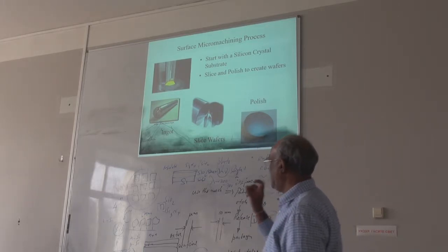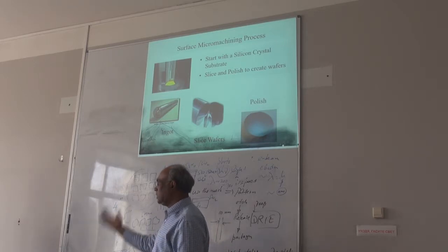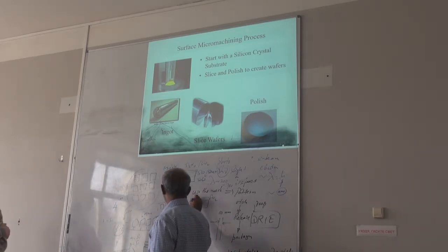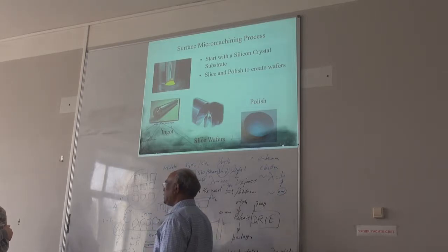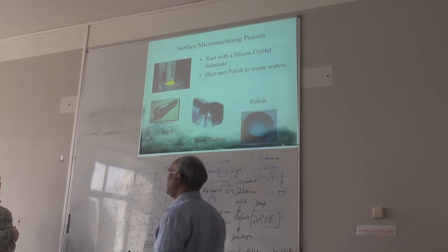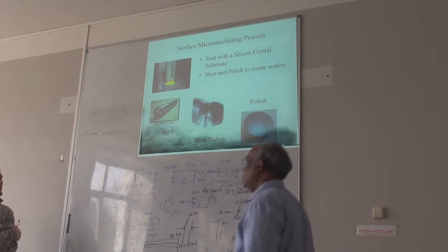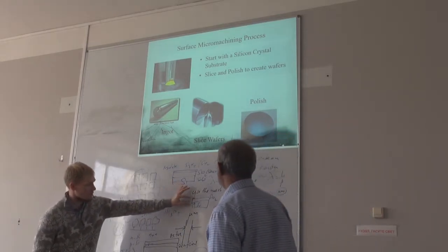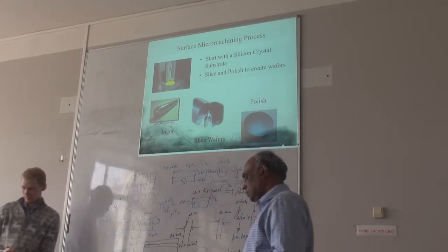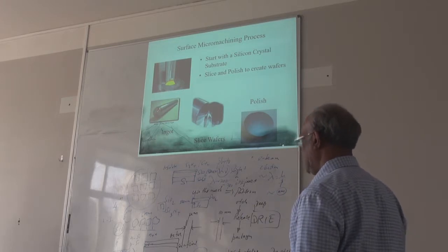But you have to define how much silicon dioxide you want. You can specify if you want, say, 500 nanometers of silicon dioxide, but then it's a little expensive. We usually buy only the silicon wafer. We do oxidation in our clean room. You do oxidation? Yes. And you can control the thickness? Yes, we can control that thickness. We only buy just silicon without oxide.